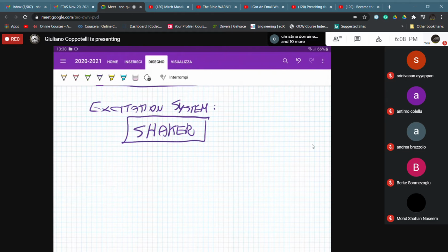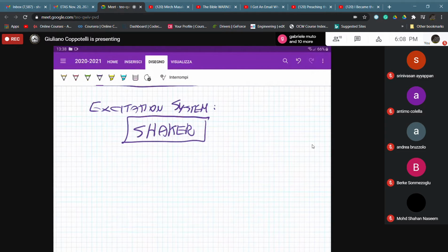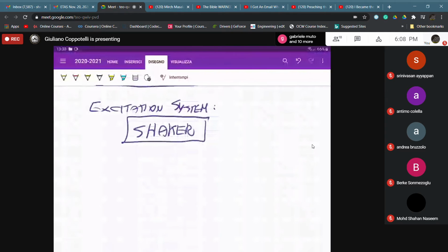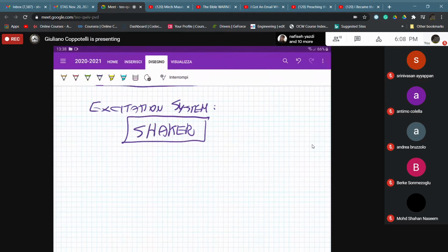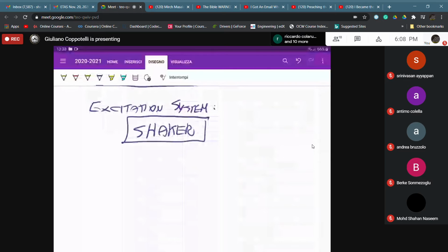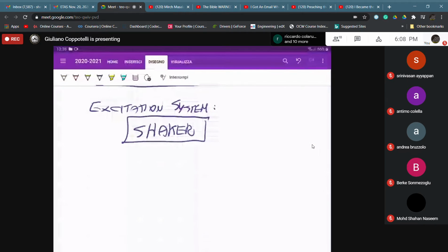Okay, so with the magnetic interaction, we can feed your coil with your desired mechanical wave in the shape of an electrical wave. This electrical wave is interacting with the magnetic field, and therefore the reaction to that is a motion of the movable rod.